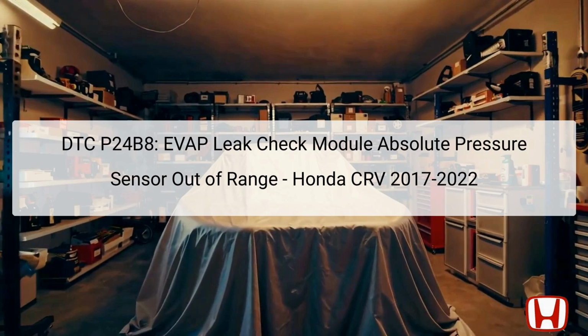The code P24B8 refers to an issue with the EVAP Leak Check Module absolute pressure sensor, specifically signaling that the sensor is out of the expected range. The EVAP system plays a critical role in preventing fuel vapors from escaping into the atmosphere. It does this by utilizing a leak check module that monitors the absolute pressure within a certain specification. Commonly located near the engine bay, this component interfaces with the powertrain control module, PCM, and other crucial sensors.